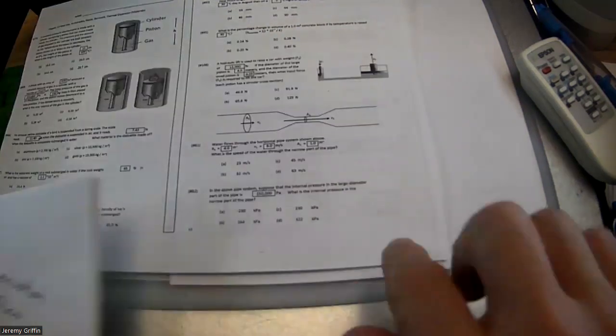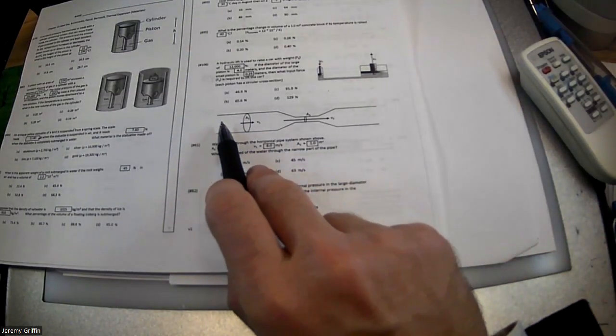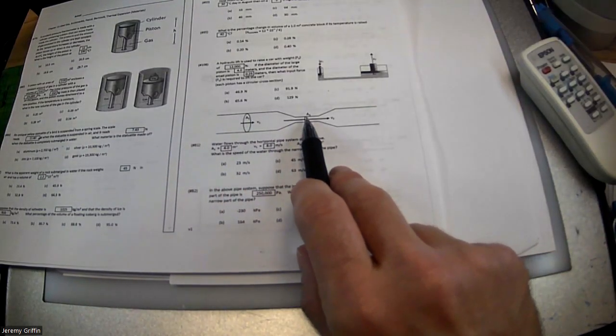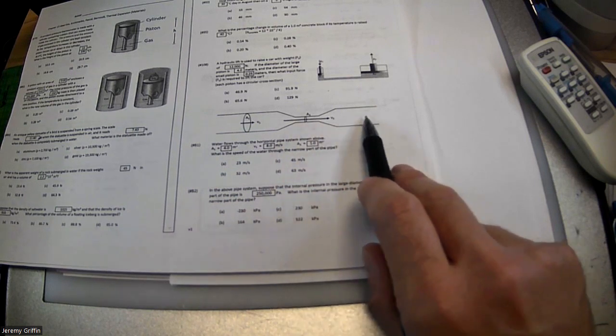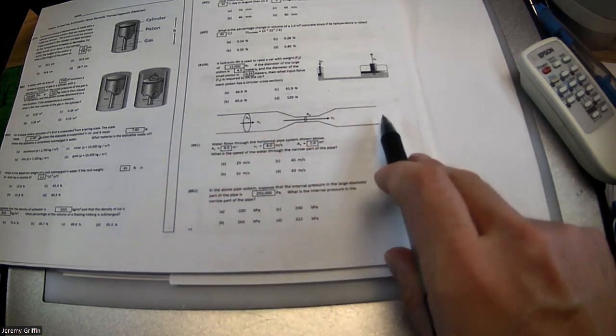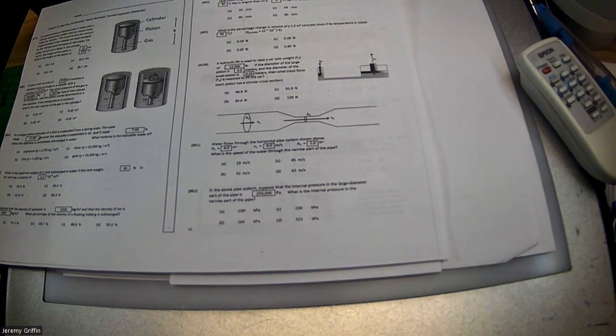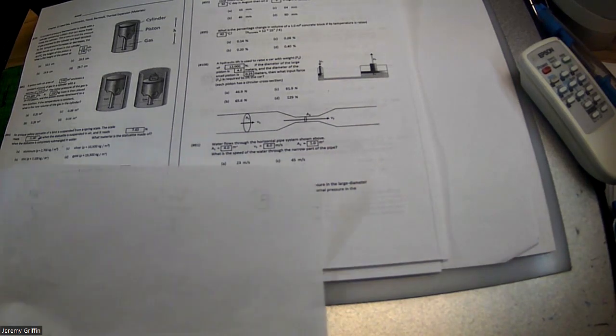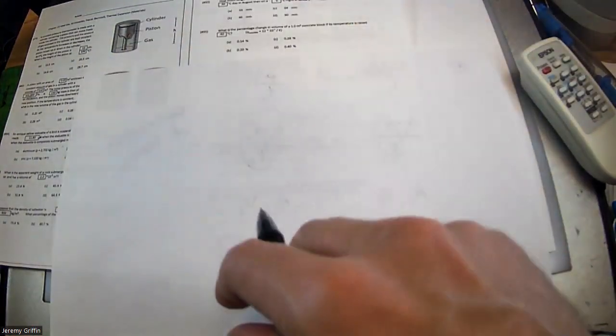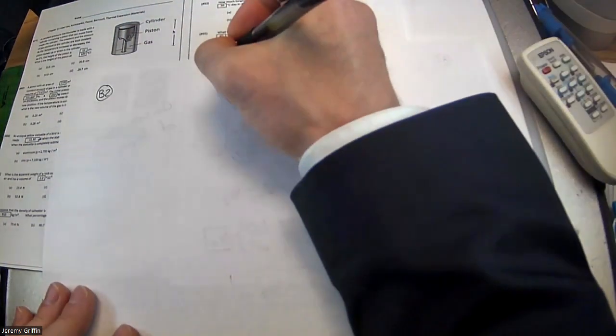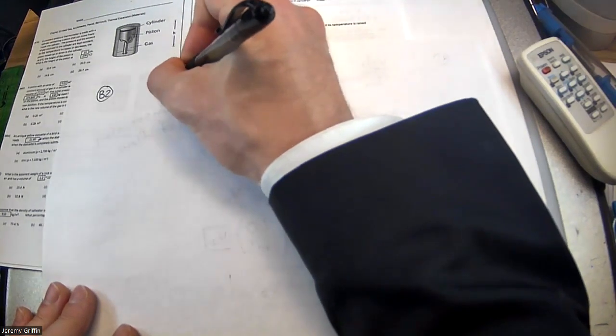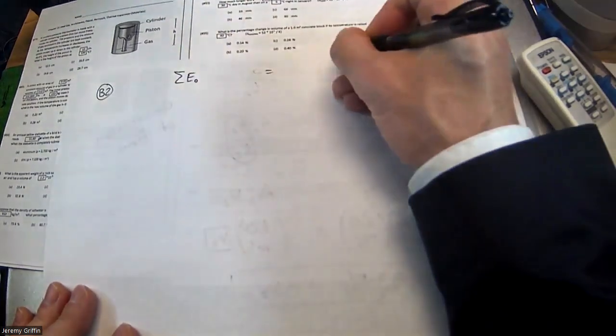I'm thinking back to this pipe system, if you're a fish swimming around, you probably feel a high pressure here and then a low pressure here, almost like you'd gone to the surface of the ocean. And now you're back in the ocean deep, even though there's no height change, right? Okay. So why is the pressure changing? Well, the best explanation, I think, is actually to start with the conservation of energy, and I'll derive Bernoulli principle for you guys. Now, you guys have seen Bernoulli principle on a PowerPoint slide, but I'm going to derive it for you here. Okay, and then we'll plug in stuff and apply some numbers. So I'm going to go back to a few months ago. Do you guys remember conservation of energy? Sum of energy initial equals sum of energy final.